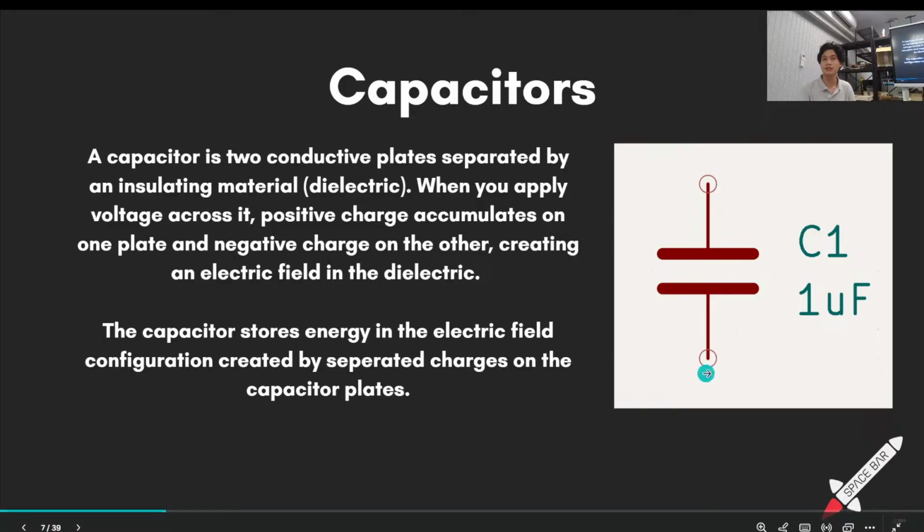So current through a capacitor is not related to voltage; it is related to the rate of change of voltage. Okay, this is very important. Does everyone accept this? Current through a capacitor is proportional to the rate of change of voltage, and not proportional to voltage. Because as the voltage goes up or down, the charge in the plate changes. As charges flow, there is a greater voltage across these plates, because the E field here gets stronger. So when current flows, the voltage changes. Am I making any sense right now? We're good, right? Current is proportional to the rate of change of voltage. This is the only thing we care about from that slide.